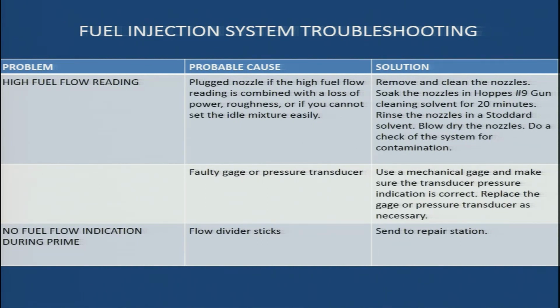Another probable cause of this problem might be a faulty gauge or pressure transducer. So the pressure transducer or the gauge might be faulty. In that case also, we may encounter a high fuel flow reading.